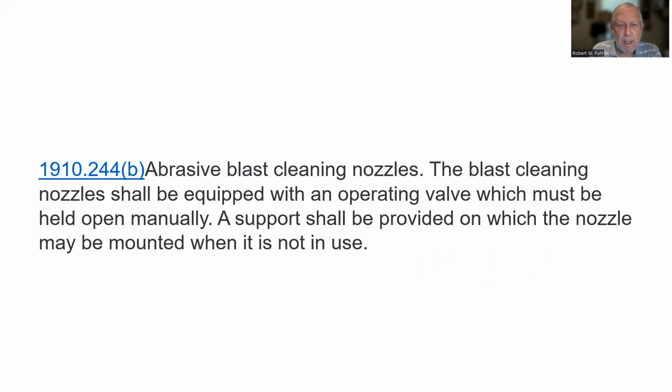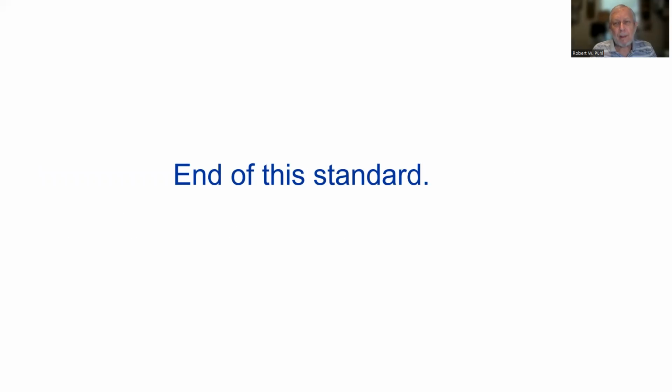Very common sense. Abrasive blast cleaning nozzles. The blast cleaning nozzle shall be equipped with an operating valve, which must be held open manually. A support shall be provided on which the nozzle may be mounted when it's not in use. So in other words, a blast cleaning nozzle is kind of like a dead man switch. If you let go of it, it's going to go off. And that's all of that standard too.